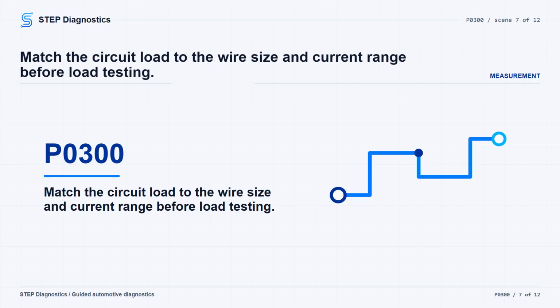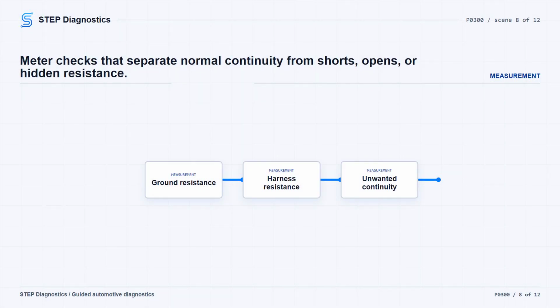Larger conductors matter too. Conductor sizes 20 gauge, 0.8 mm, or larger are generally used to carry 1 ampere, 1000 mA or more. For ground and harness resistance checks, expect less than 2 ohms for most small diameter 18 gauge and smaller wires, and expect less than 2 ohms of resistance for most wiring harness circuits. Remember the limits of the meter.